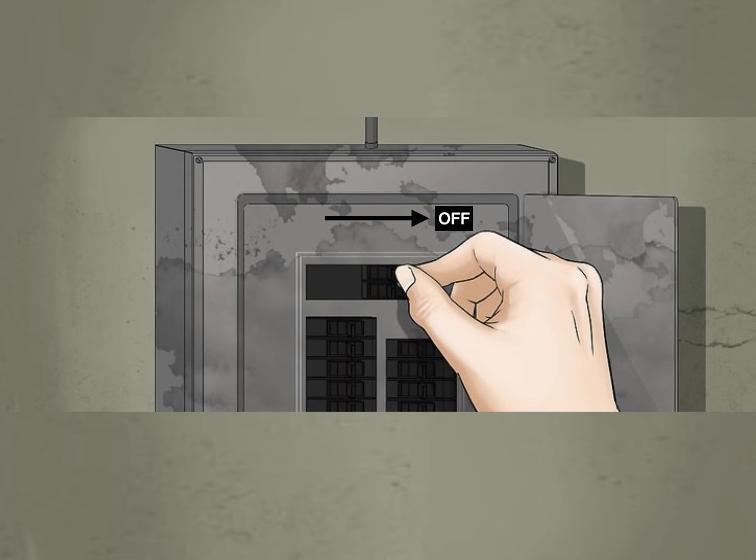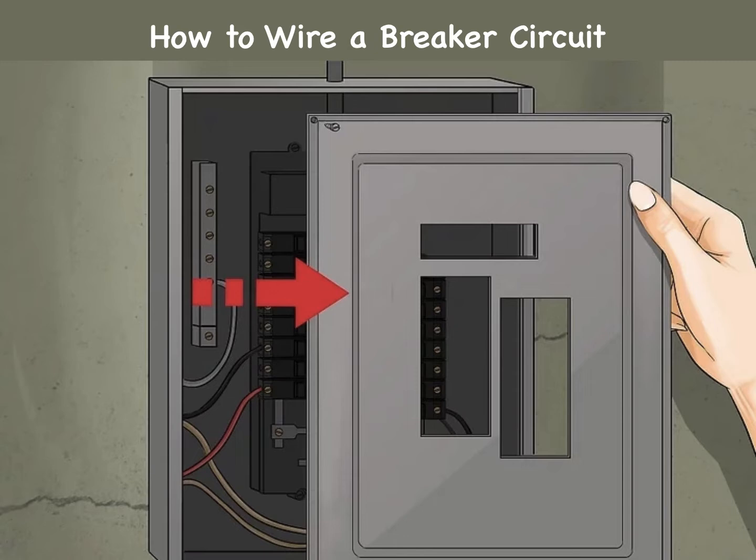If you are to do any work inside the main breaker panel, the first thing you must do is switch off the main power switch or breaker. This is usually, but not always, at the top of the breaker panel. It should be the largest breaker in the panel, and will also have the highest ampere rating in the panel. Take the cover of the breaker box off.